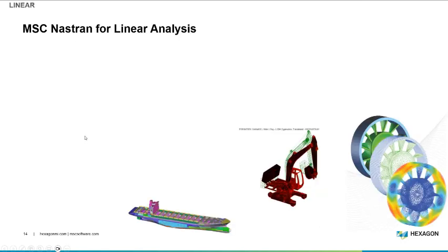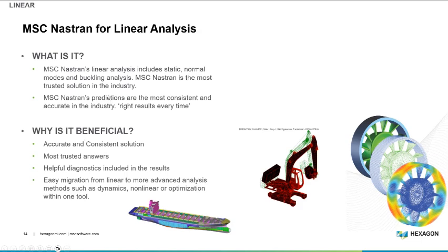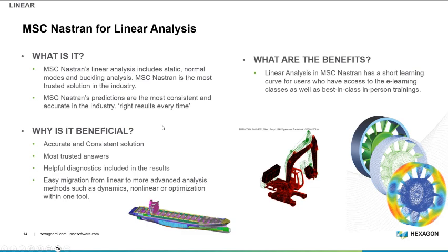If you scan through some of these, we look at linear analysis examples. So what is it? Well, linear is pretty much the bread and butter of most structural engineers, where we assume that stuff is linear. And for a large category or group of analysis types, it makes perfect sense. We don't want it to go plastic unless there's contact. There's nothing special there. The only other possibility, geometrically nonlinear, usually has to do with thin plates with some kind of a pressure load on top of it. It's oversimplified, but still, it's very efficient to run something linearly if it is.